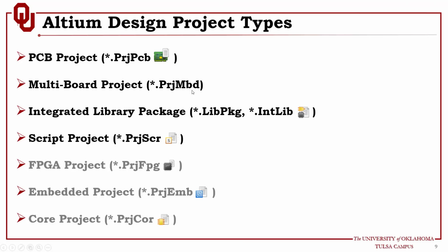So this is multi-board project. You can create, let's say, a RAM, create a wireless module, create a motherboard, which is the baseboard, create a controller, and then these are separate projects. After you finish each one of these, you can import them into something called multi-board project. And this multi-board project will do an assembly for these from a high level. It's not design level, but it's from a high level perspective.